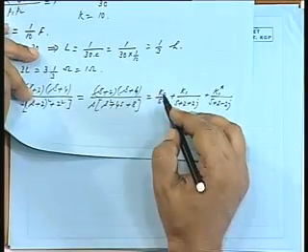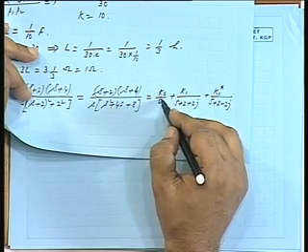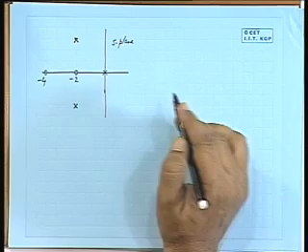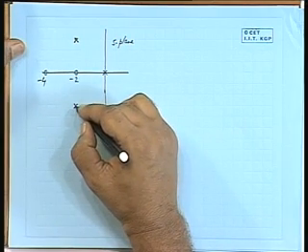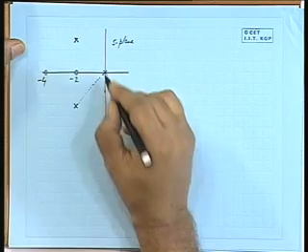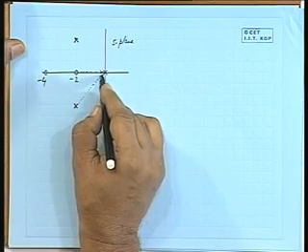So, when we compute k0, the residue corresponding to the pole at the origin, you draw vectors from other roots, that is all the zeros and poles, up to that point.